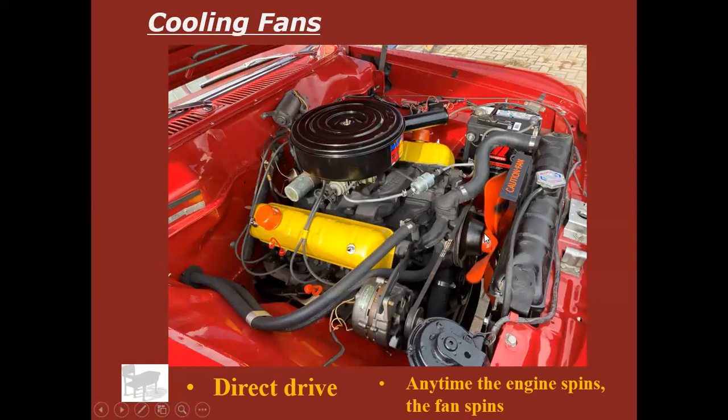As fast as that water pump spins is as fast as that fan spins, all the time, every time. Very reliable method of having a cooling fan. Probably my favorite. They're just idiot proof, I guess you'd say. They always work. But they're a little bit hard on the water pump bearings because they're always dragging. They're always pushing air, so it can be a little bit hard on the water pump bearings, and they waste gas mileage and horsepower.